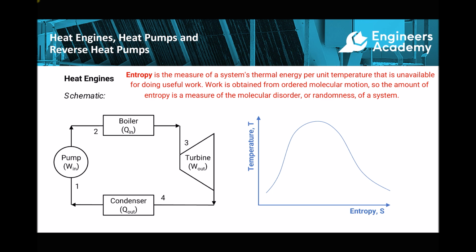So the entropy, if you like, remains in the system. We mentioned that within our turbine that was an isentropic process or a constant entropy process. So what we're basically saying there is we're removing the useful work, but the non-useful work remains behind. So the expansion of our steam through our turbine is essentially an ideal process because the only energy that remains in the system or in the working fluid is the entropy or the non-useful energy.